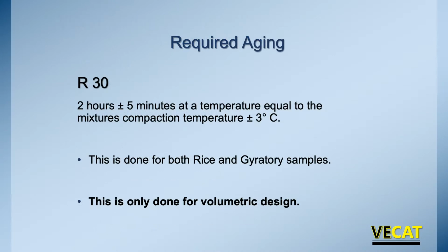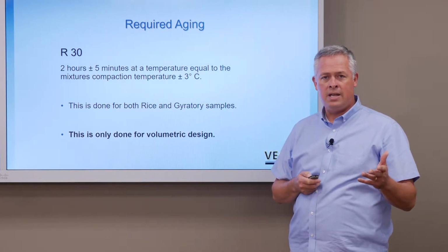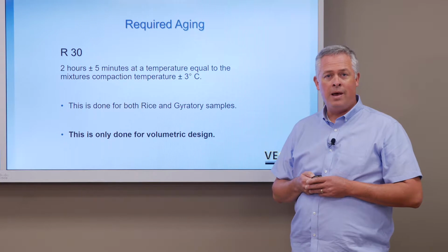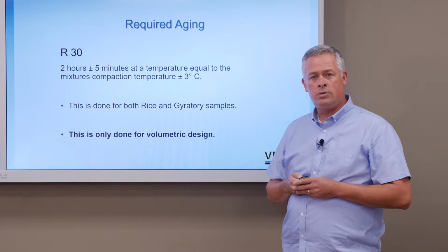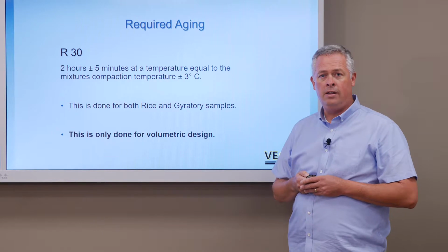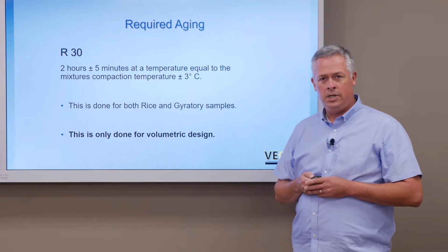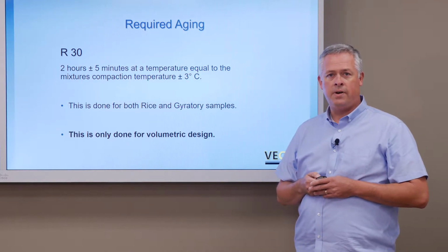Required aging is a key component of mix design. When we make mix in the field, that mix is put into a silo typically where it may stay anywhere from 30 minutes to 2 days. From there, it's going to be loaded into a dump truck and hauled to a job site. You may have a 30-minute to an hour haul there. From there, that truck is going to pull into a queue into the construction zone. He may sit for 15 to 30 minutes there before he's actually unloaded into the paver and it's actually laid with the machine. During that time, a lot of absorption takes place of the liquid asphalt into the aggregate.